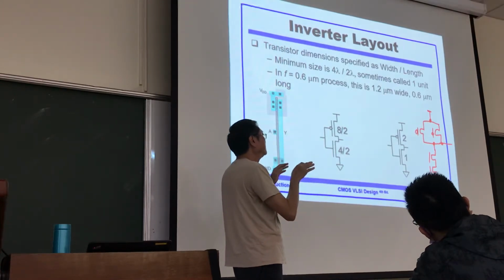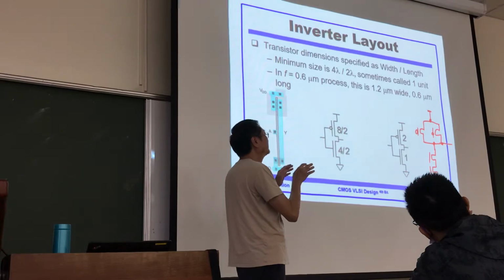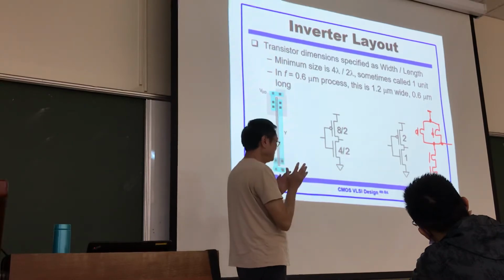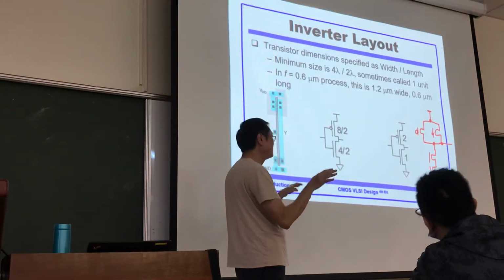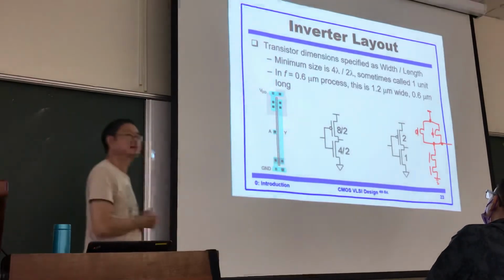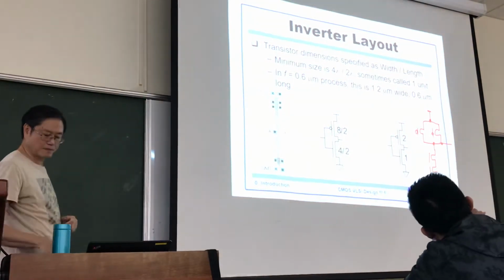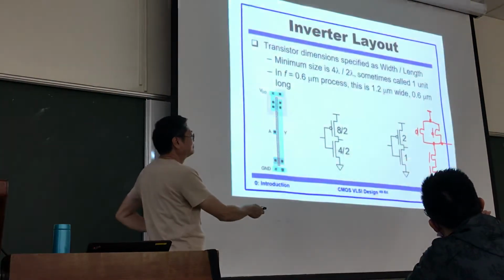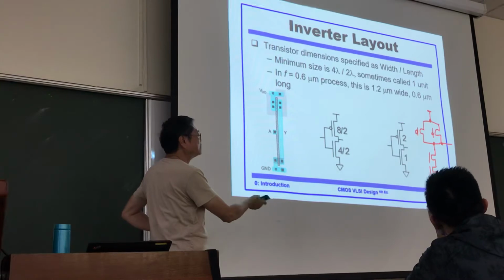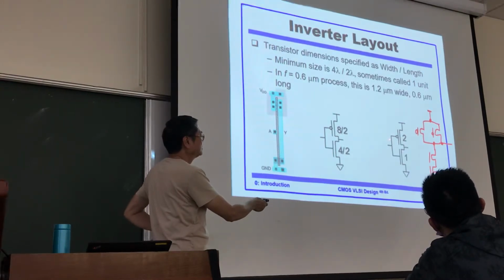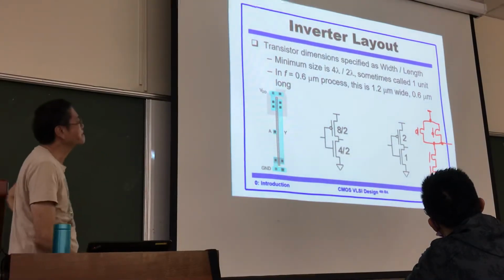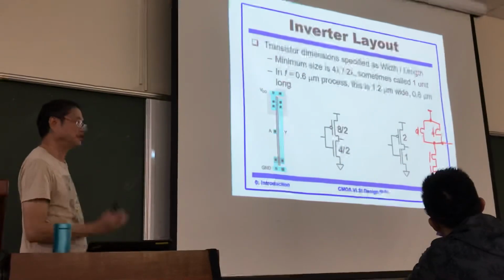Taking the pessimistic case, what is the output switching 0 to 1, 1 to 0? If they are both the same speed, what is going to be your transistor size? Can you tell me? One is the minimum. Minimum channel length, also minimum channel width. Two is double the width, also minimum channel length. To compensate, how about two input NOR gate? Any suggestion?